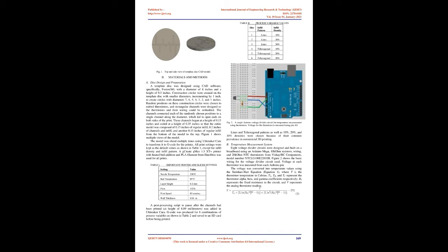Generalizing their results supports the idea that plastic has a much greater impact on heat transfer and overall temperature distribution of a 3D printed object than air. Hahn supports this in his study on the thermal conductivity of PLA objects and found that the thermal conductivity depends nearly linearly on the volume infill percentage. He noted that the only major discrepancy between the results, although being minimal, could be due to the natural convection caused by air in enclosed spaces.